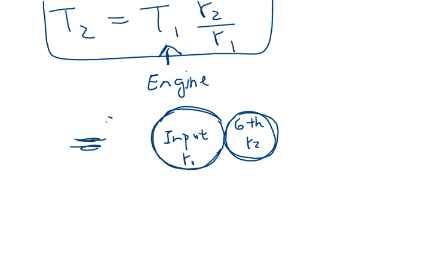If you're cruising at any speed, you're in your highest gear. And how much torque, how much twist do you need on your wheels if you're already cruising? Well, you've got all this momentum. You barely need any torque to keep that car moving. So it's perfectly fine. Your high gear can be really small. You don't need a large amount of torque when you're in your high gear.